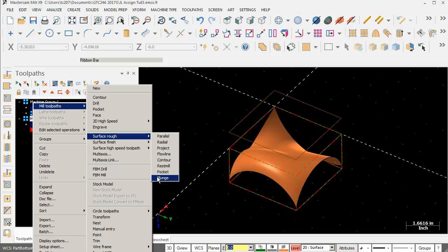And again, if you want to experiment with the other items, I want to give you the base 3 that will make up the majority of the programs, and then as you need additional items, maybe the 1/2 inch tool couldn't get into a corner or something, you have to go to a smaller tool. Then that would be where we'd go over to rest mill so that it could take a 1/4 inch and go do a clean out. Flow lines are going to follow specific curves. Radial is kind of one of those.